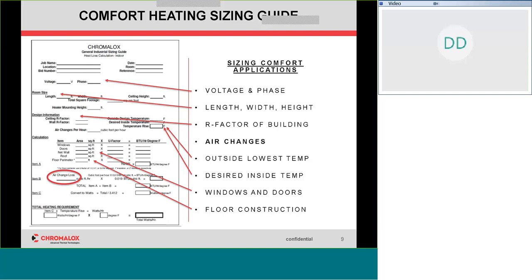R factors, you saw before where sometimes you get the U factor of an item. U is just 1 over R. They're basically insulation factors. Important to remember, though, that insulation factors are usually rated on thicknesses. So the 1 inch, 2 inch, 3 inch, and I'll show you an example of that in a minute.